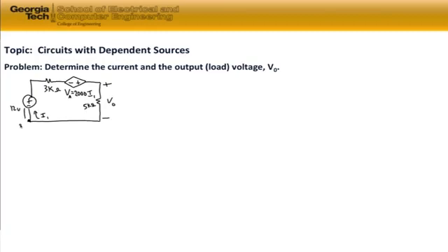And we see that if we do that, the first thing we encounter is a minus 12 volts associated with the source. So again, we're doing Kirchhoff's voltage law, and it's clockwise around the circuit. So it's minus 12 volts associated with the voltage source on the left-hand side of the circuit, and then we have the voltage drop associated with the 3 kilo ohm resistor, and that's going to be I1 times 3 kilo ohms. And using the passive sign convention, we designate the voltage drop as plus to minus across the 3 kilo ohm resistance.